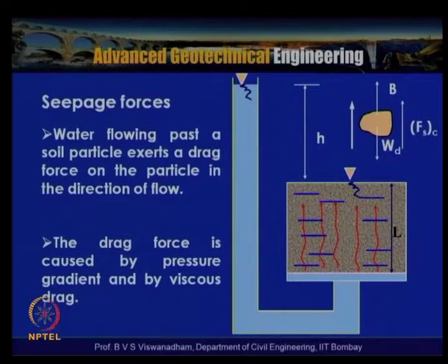Now, we have discussed that when water flows from a higher energy, higher head, to a lower head, it exerts energy on soil particles in the process of flowing. These forces which are exerted on soil particles are called seepage forces. So, water flowing past a soil particle exerts a drag force on the particle in the direction of the flow.